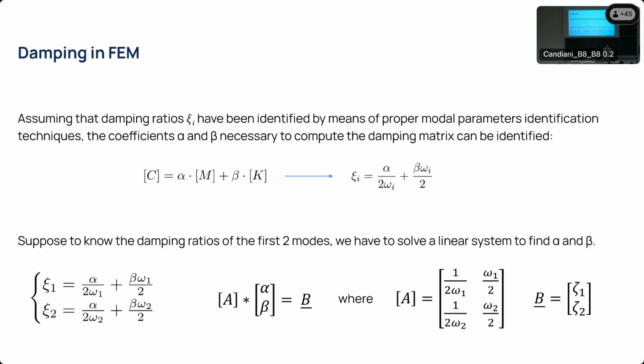Remember that sometimes we will be able to find precise values for those parameters because, if we have, for example, two modal damping ratios, it's quite easy to find them. Sometimes we might be forced not to find exact values for those parameters, but to use a least square approximation, because maybe we have the modal damping ratios of several mode shapes that, for example, you obtain in an experimental campaign. So let's say you take your helmet, you go into the field, you put a set of accelerometers on a structure.